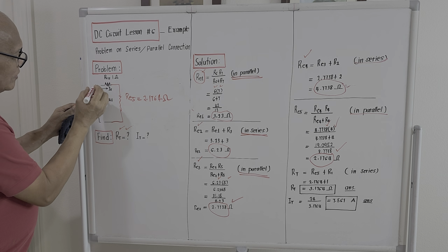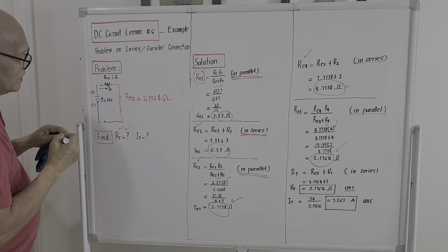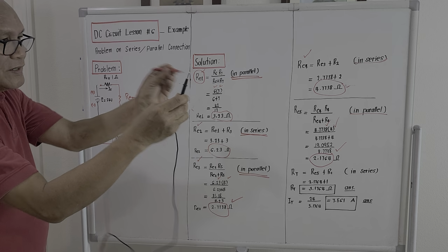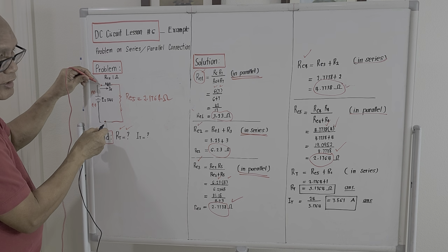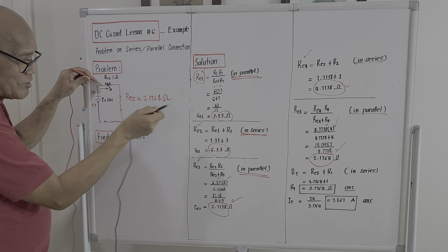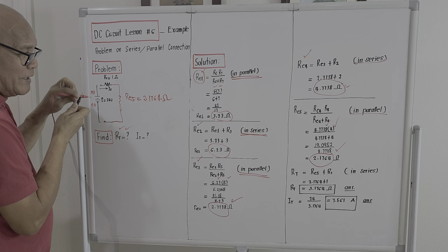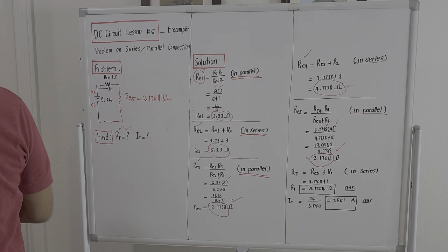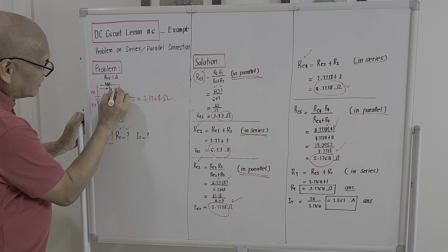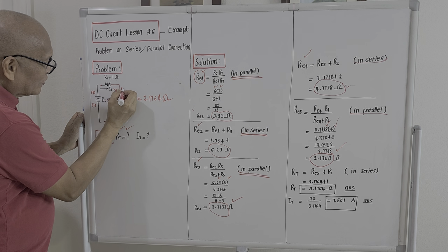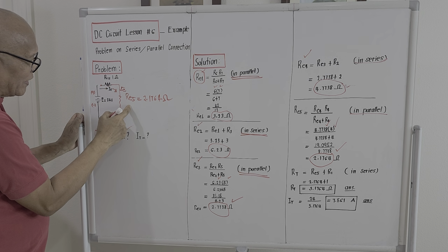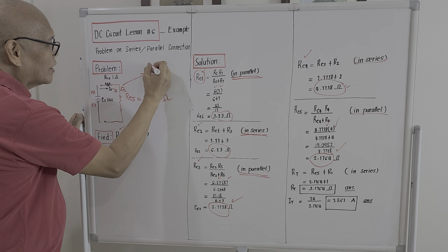And again, if we try to disconnect it here, we disconnect the power source, this will be an open terminal. If you try to get your multitester, you tap it here, you set it to the ohms rating. What you will be getting will be the total resistance of the entire circuit after the simplification. And as you can see it, this R1 here is in series with RE sub 5. They are in series, right? That will be the circulating current. Since they are in series, the single equivalent of R sub 1 plus RE sub 5 now represents R total.